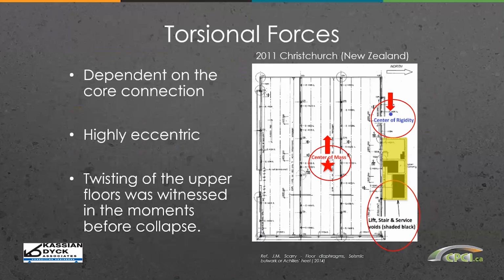So here you really have to think, as the engineer designing, how are you getting that whole shear from the earthquake on that diaphragm floor plate to the core wall? You have openings due to the elevator, you have openings due to the stairwells. If your main shear wall is the one to the right in this figure, way away from the building, how are you transferring those forces through the landings in that area?